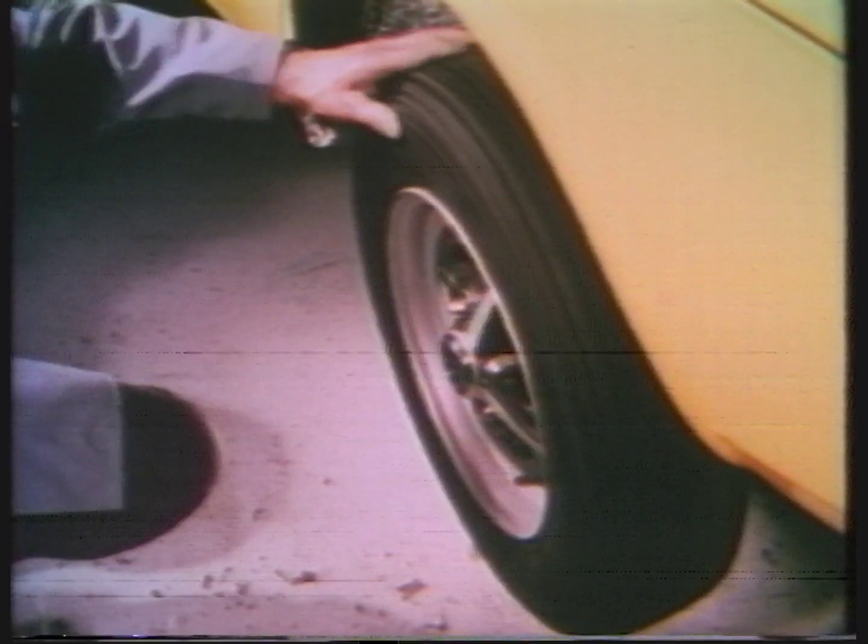On all vehicles, the mechanical factor should be kept in mind during preparation for balancing. In this way, the alert technician, at an early stage, may spot damage or an irregular condition that has a bearing. When it comes to problem cases, lateral and radial run-out of tires will have to be checked to close limits. But at the initial stage of routine balancing, look at fitting beads and spin the wheel to see how it looks. This will pick out the odd case which is hopelessly out.